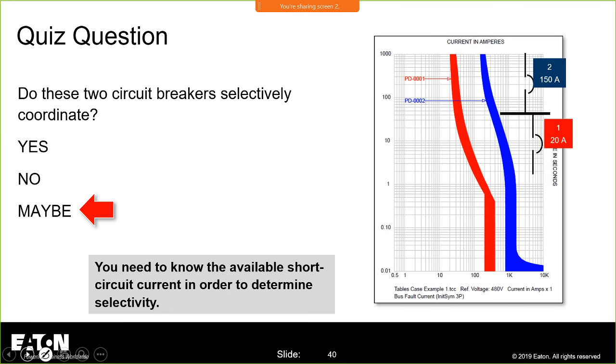What I'll do is I'll go over that when I have an electronic trip unit, because on a thermomagnetic breaker, you really don't have any adjustability. You have the instantaneous region, which is this down here, and then you have your long time pickup. Everything else is basically driven by the construction of the breaker itself. Those are thermomagnetic, and I'm going to be posting for next week a circuit breaker basics class where we're going to talk about how that curve is constructed.